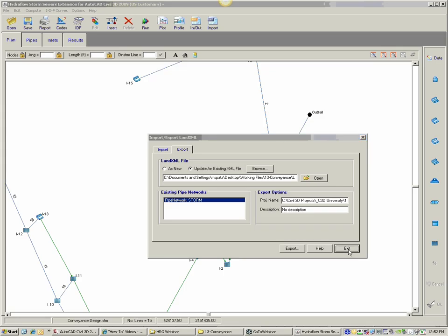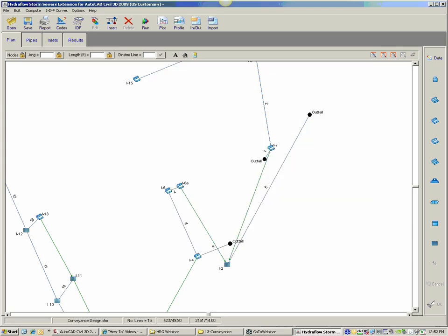So how do I do that? It is important that you and your designer get on the same page, or if you are the designer, that you get all the inlets in, you design them, and then you take them back out. If you're going to add new inlets to the line and you've made adjustments in HydroFlow, get the update back into Civil 3D first, then add the new inlets, and then bring the data back. So let's do that right now.